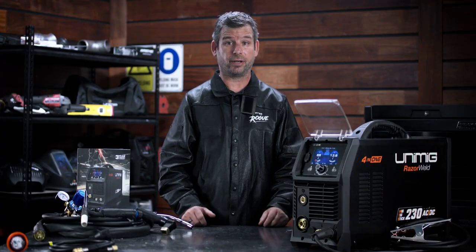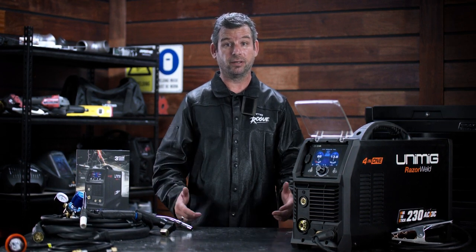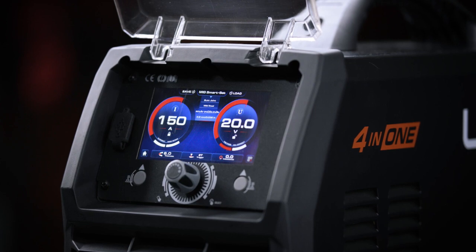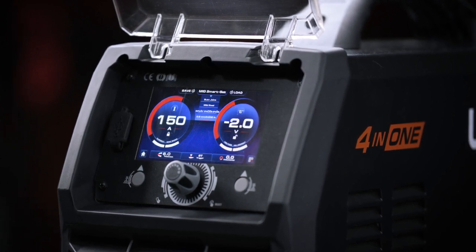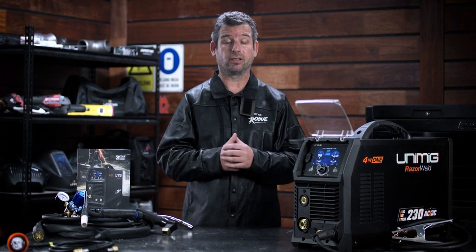If you add a voltage correction to your settings, this will remain if you then go back and adjust the current, thickness, etc. So if your voltage is 20, with a correction of -2, the -2 will remain even if you change your current and the voltage increases to 22.